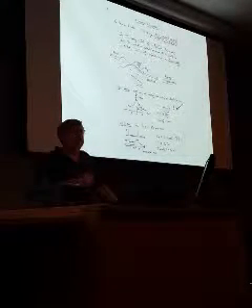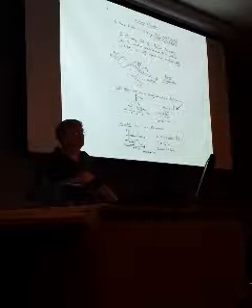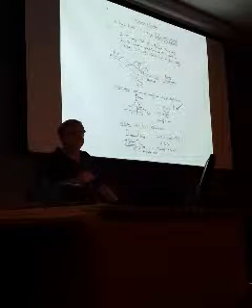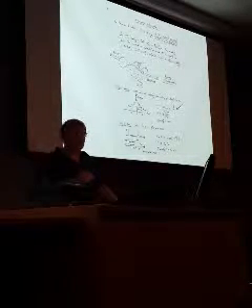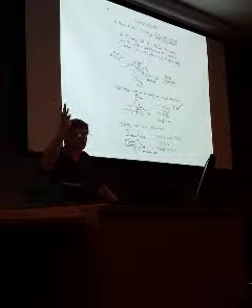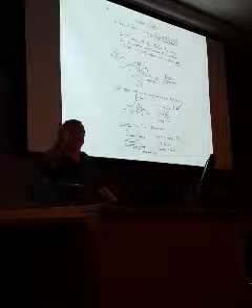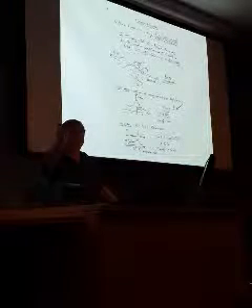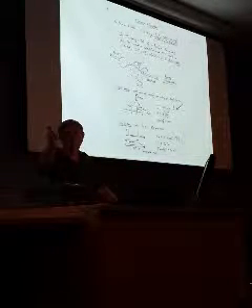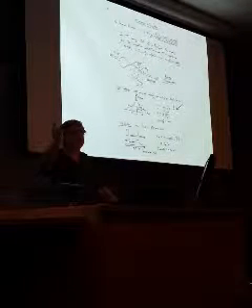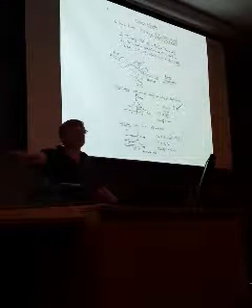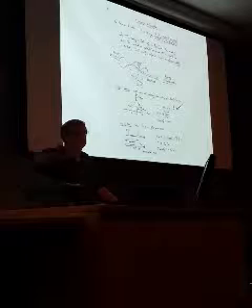What kind of element looks like that? Capacitor? Nope. No, there's no C's in this. What does a capacitor look like? What's the impedance of the capacitor at DC? If I do a DC analysis, all the capacitors go away because the impedance is zero at DC.